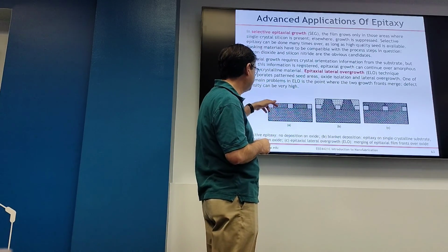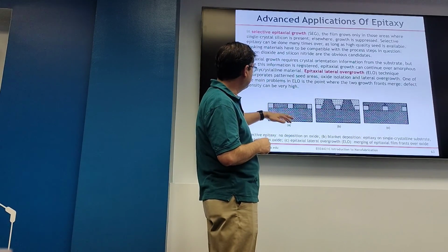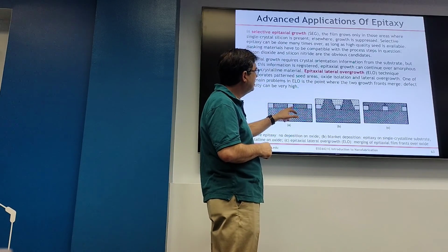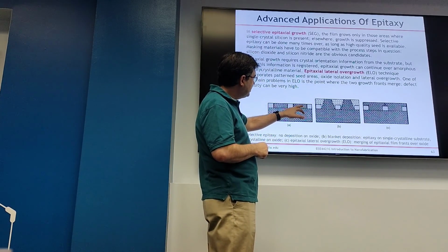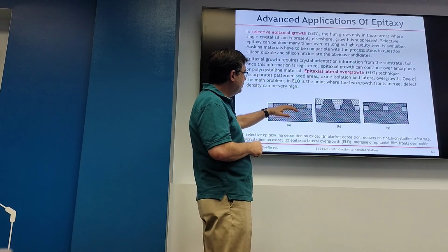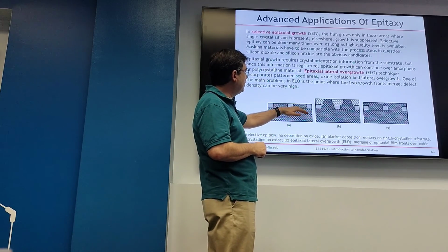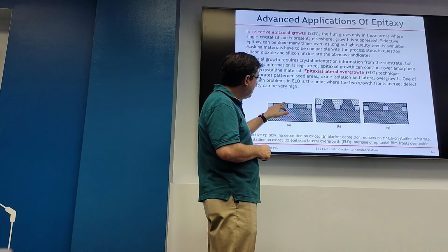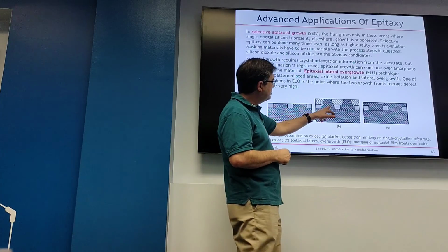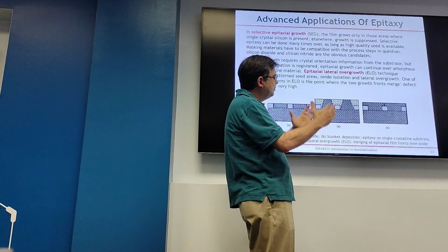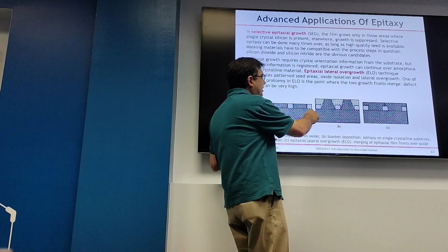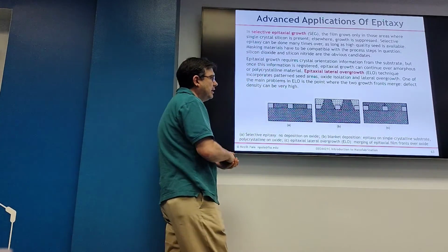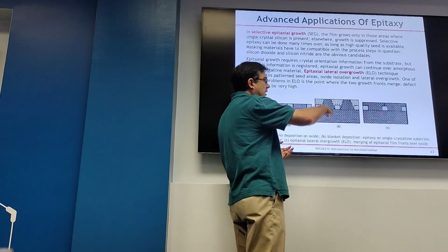This is the deposited oxide, but what is oxide is not shown. I presume this is oxide. So this is the thin material. You deposit it first. Let's say it's thin gallium nitride, and you can etch it. You put oxide, and then you grow. When you start growing, as you see here, you first will have some pyramid-like structures, but then it will grow over this layer, the oxide mask layer, laterally and vertically.